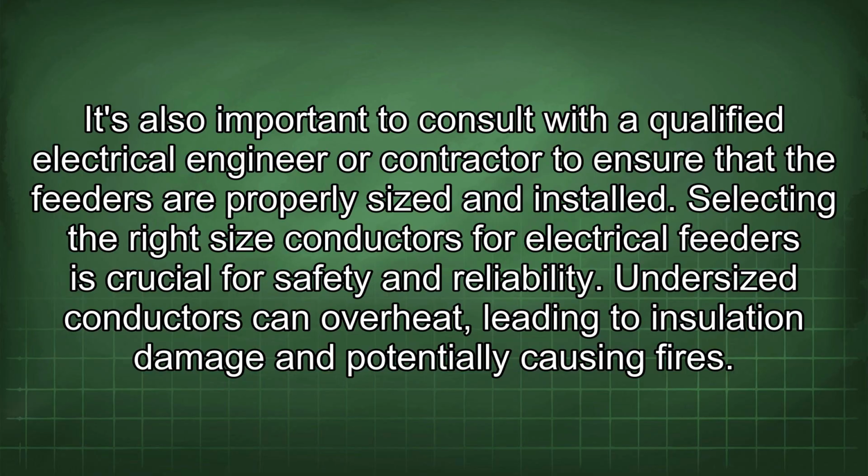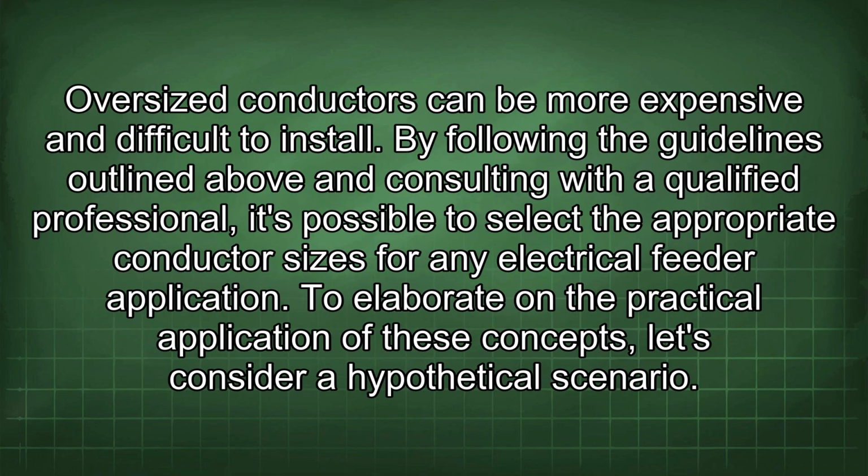Undersized conductors can overheat, leading to insulation damage and potentially causing fires. Oversized conductors can be more expensive and difficult to install. By following the guidelines outlined above and consulting with a qualified professional, it's possible to select the appropriate conductor sizes for any electrical feeder application. To elaborate on the practical application of these concepts, let's consider a hypothetical scenario.